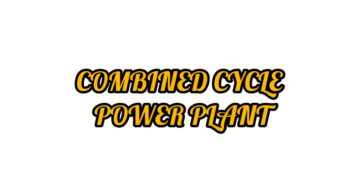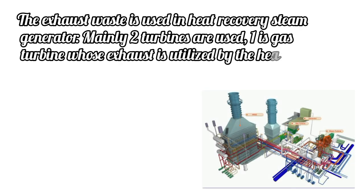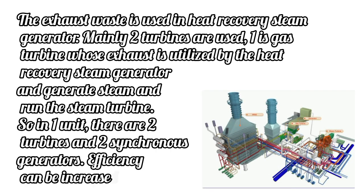Combined cycle power plant. The exhaust waste is used in heat recovery steam generator. Mainly two turbines are used. One is gas turbine whose exhaust is utilized by the heat recovery steam generator and generate steam and run the steam turbine. So in one unit there are two turbines and two synchronous generators. Efficiency can be increased by 50 to 60%.